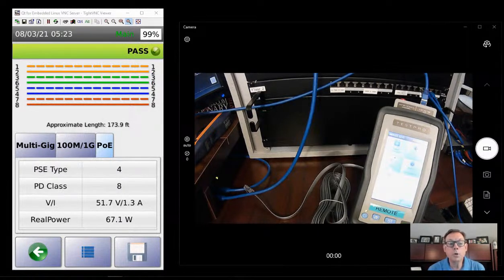If we're referring to what could cause that resistance unbalance, it could be the quality of the cable. It could be termination practices, which would also typically lead to other components of the overall Cat6a test failing. For instance, if at the point of termination you had an extra couple inches of pair 1 versus pair 2 versus pair 3 versus pair 4, and made each a different length before you terminated them, that would be a little bizarre, but it would cause some differences in resistance.